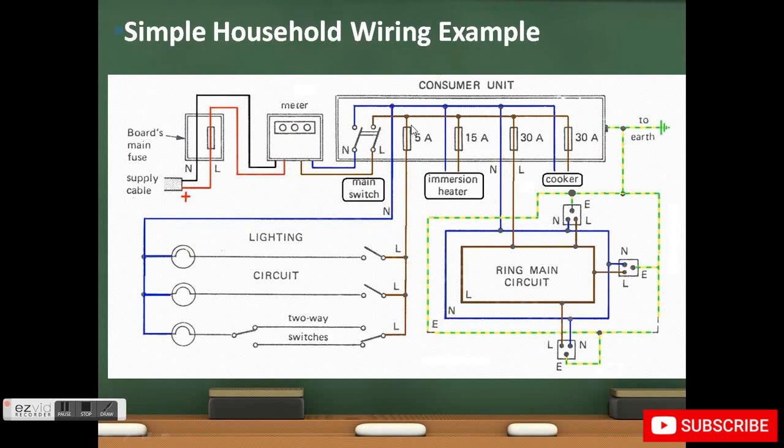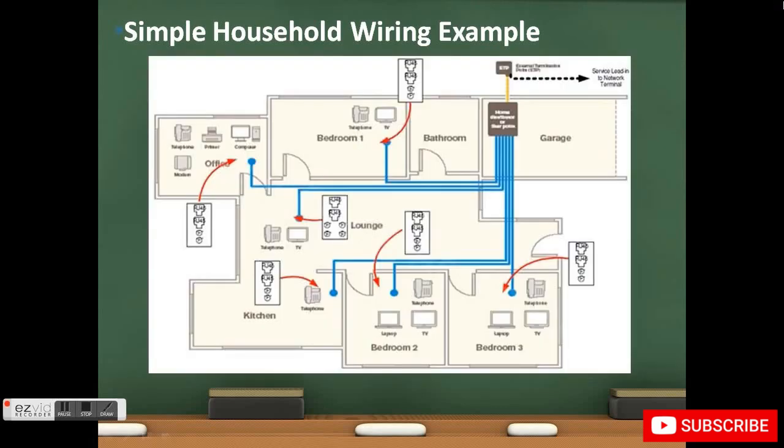This power supply is then divided into 4 branches. Each has its own fuse to protect the devices underneath them. So let's say your power outlet has stopped working. From this diagram, you can see that your 30 amp fuse has probably blown, and there's likely a fault in your main circuit.